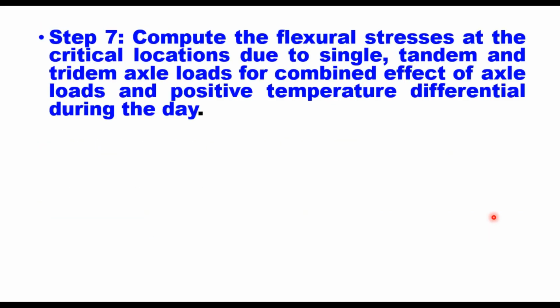Then the seventh step is to compute the flexural stresses at the critical locations due to single, tandem and tridem axle loads for the combined effect of axle loads and positive temperature differential during the day.